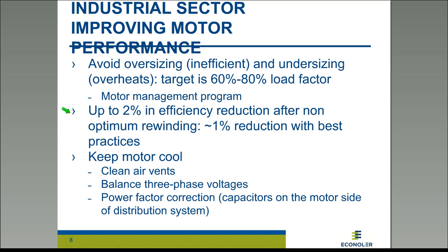Another point that is very important to understand is that when we start to implement premium efficiency motors or even energy efficient motors in the market, we must be very careful about the repair practices that are used, because several studies have demonstrated that a high efficiency motor that is repaired in a shop that doesn't use the best practice and the appropriate equipment can lose up to 2% in efficiency after non-optimum rewinding. If you apply, on the other hand, the best practice, you can achieve less than 1% reduction.